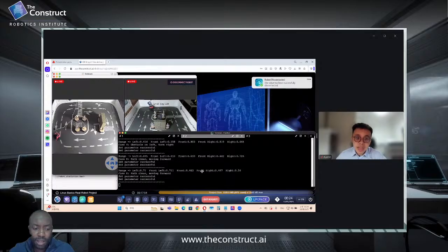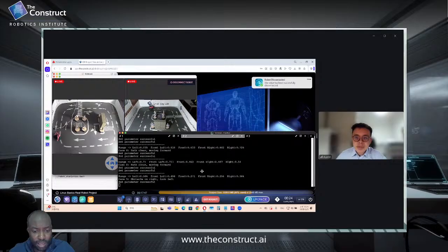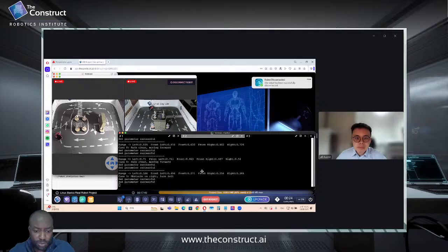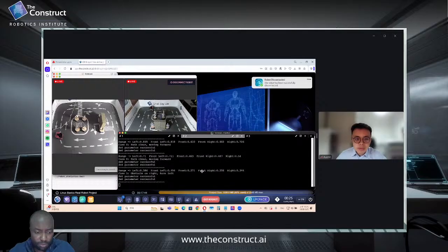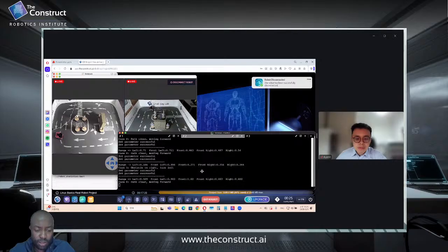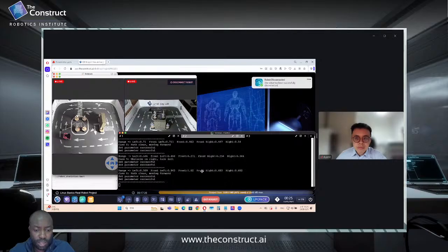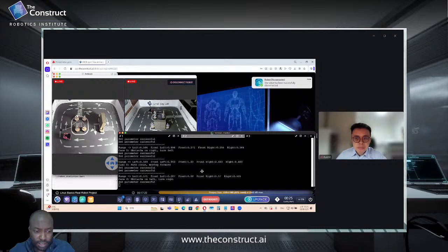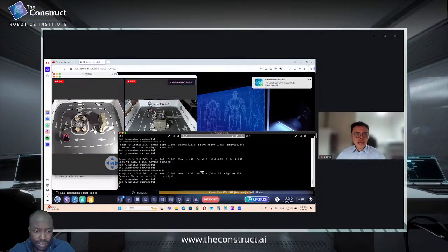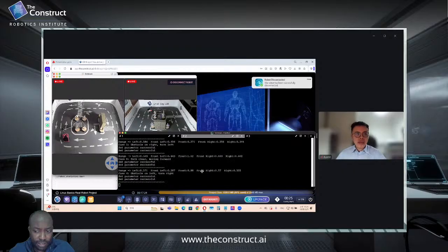Okay. I think for us to really get to the bottom of this, you added a sleep after setting the value, right? After setting the angular velocity or linear velocity to a particular value, you added a sleep. Why did you do that? This is the foundation of the question. Actually, I just wanted to make it safe between two commands.